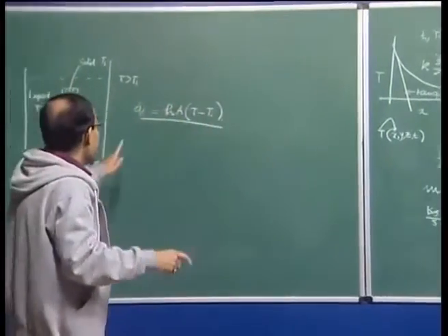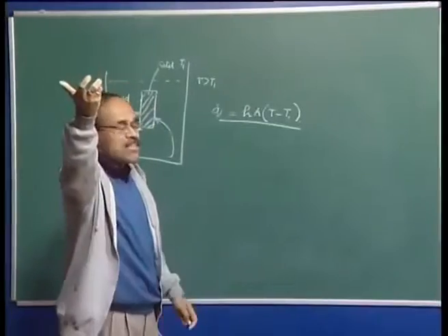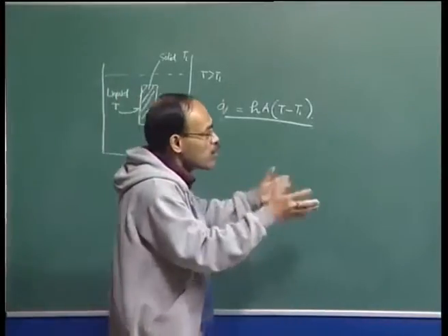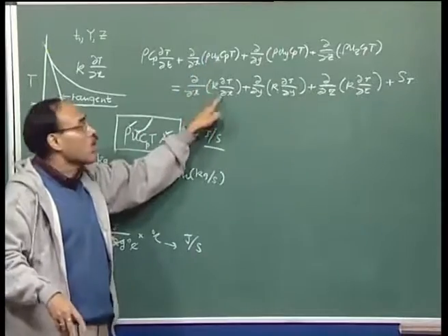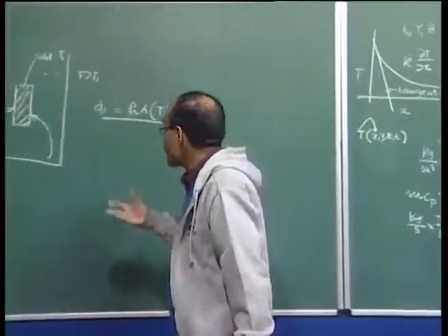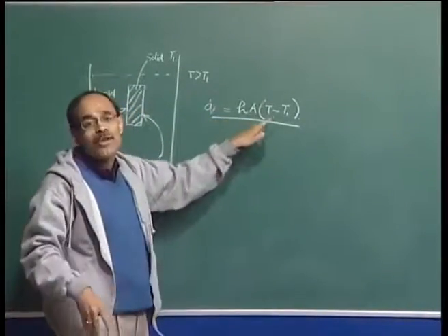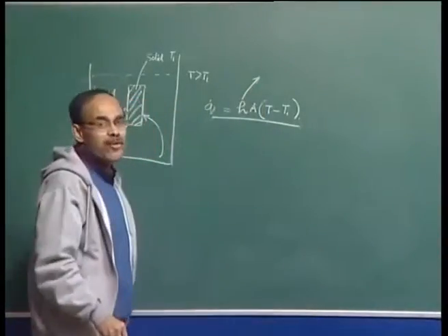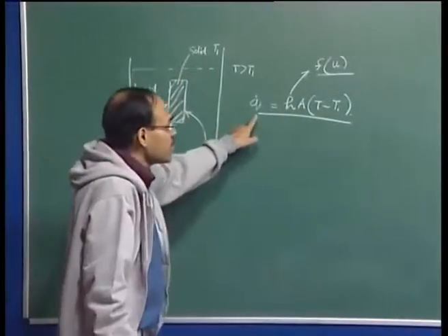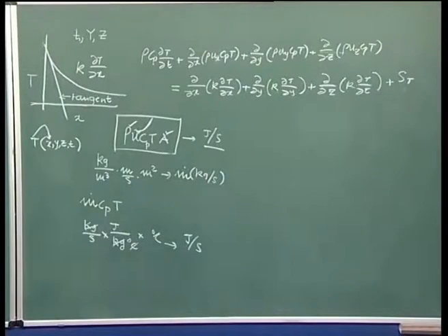And it is found out that the heat flux under those conditions, from a hot plate at what rate heat is flowing to a liquid which is flowing past the vertical plate, we can solve the convection diffusion equation, which is the convection diffusion of thermal energy. So, you can solve a simplified version of this energy equation in order to get the heat flux, and it is found out that such a heat flux solution can be cast into this particular form itself, in which this parameter, which is called the heat transfer coefficient, is a function of the velocity of the fluid. So, this result is obtained for some classical benchmark solutions by solving this kind of a governing equation.